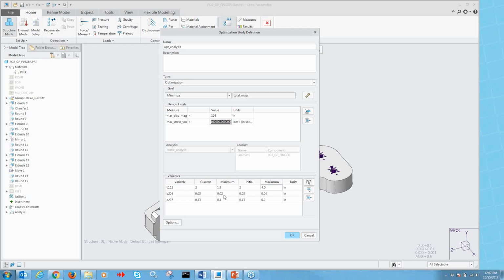For the ball diameter that we had there, 0.02, let's go up to 0.05 on that size, 0.03. And then let's go for the values here on this one. Let's set those values. We got the 0.13 to begin with. We'll go 0.12. And then we're also going to set a max value here, and let's go to a max of 0.15. All right, so we have all of our controlled variables here, what we want to control and optimize. So let's go ahead and select OK.